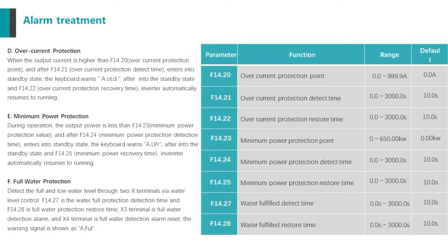Considering the protection range, the alarms are mainly displayed according to the signal trigger sequence, especially the low frequency alarm, sleep alarm, and minimum power alarm. Whichever is triggered first, the inverter will display that alarm. Like if the voltage is lower than the protection value but the power is still enough, or you cancel the low frequency protection, this time the inverter will first display the sleep protection.